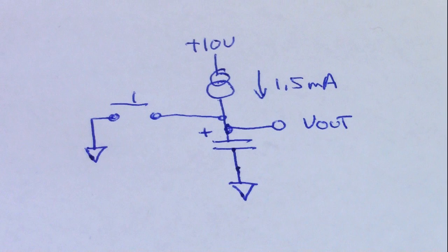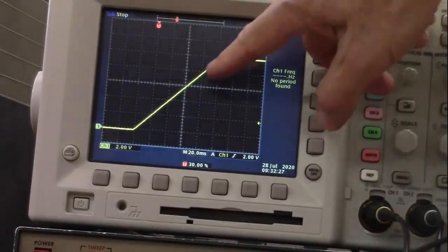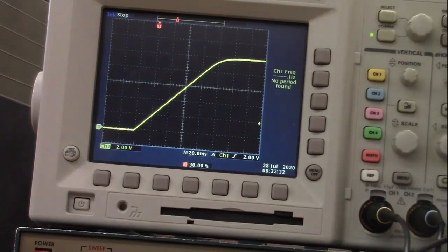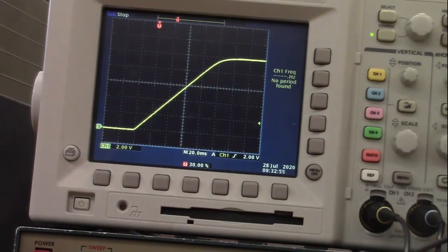And what's happening is, as the voltage across the capacitor increases, the voltage at the current source is decreasing, and at some point, the current source just stops acting as a constant current source. And obviously once we get to 10 volts, there's no way the current source could continue to pump current into the capacitor, because if it did, it would imply that the current source can create current out of nowhere. Indeed, we need at least, it looks to me, about a volt or so across that particular current source. It's made out of a kind of transistor that needs a volt or so to work. So this shows us that I equals C dV/dt.